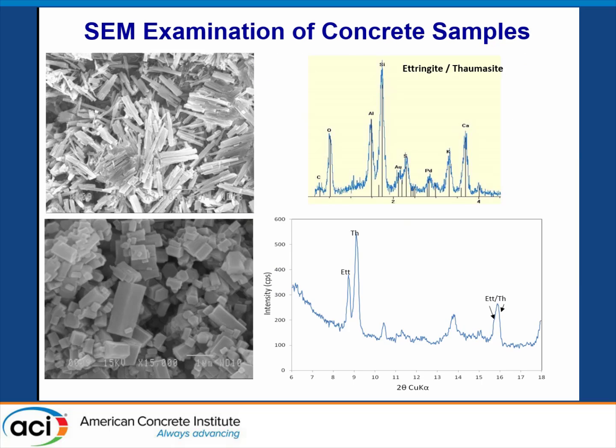Here you have an XRD pattern showing that both ettringite and thaumasite are present in the reaction rim around the oxidized particle. Both are needle-like minerals. Thaumasite is shorter than ettringite, but most of the time both are mixed together.